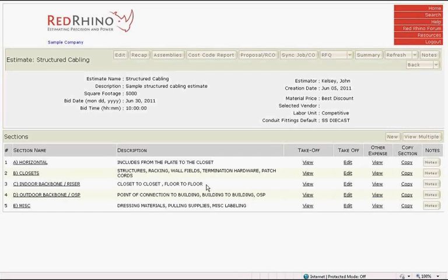components are included here. Next is section C, called indoor backbone or intra-level backbone. These are materials that go from one closet to another closet or from one floor to another floor inside a building. They may be either plenum rated or non-plenum rated in some sort of path structure. It includes your various multi-strand cables, multi-pair coppers, and some riser-rated interducts, and certain coax cables.